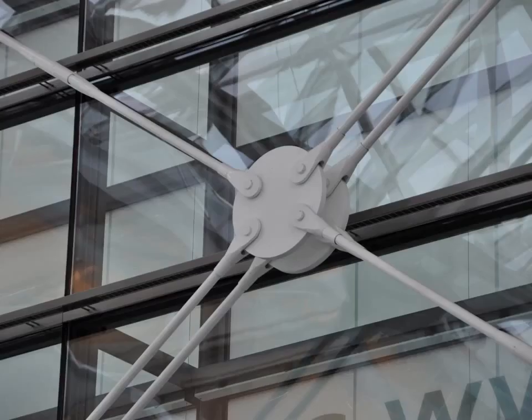The designers decided to use pairs of tension connectors to achieve the cross-bracing as part of this design. If you look to the upper left-hand rod, you can see a very slender turnbuckle. These systems must be installed loose and tightened in place using the turnbuckle.